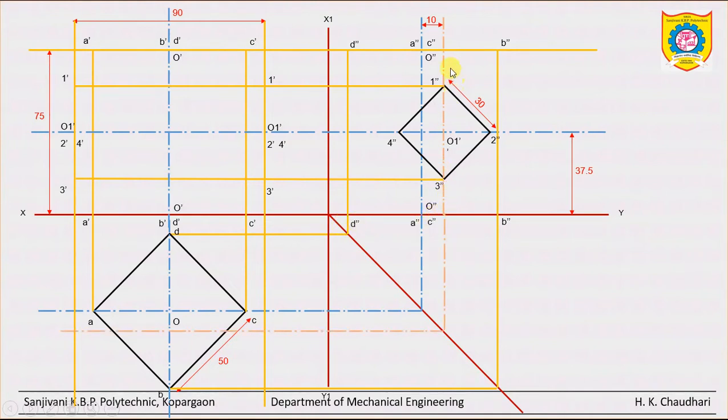See, we are drawing the top view of this horizontal prism. So what we have done here is just extend this axis. Now this red color is the position of the axis for the horizontal prism. Now it is somewhat different than the previous problem. So just take the projection from point number 4 in this way. Similarly, from point number 2, take this projection.